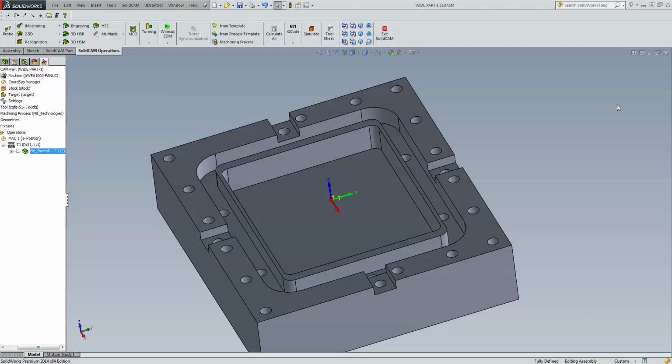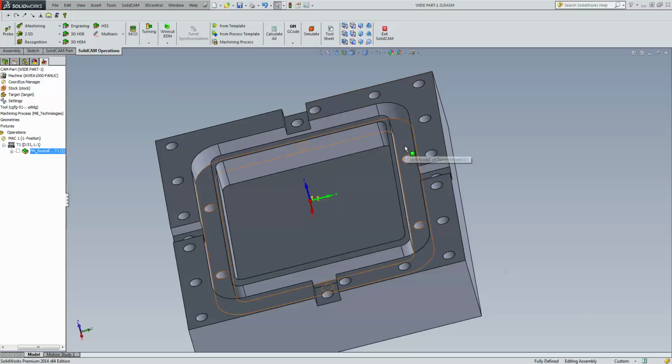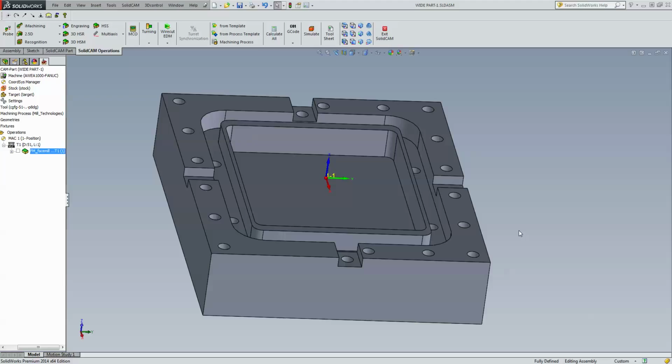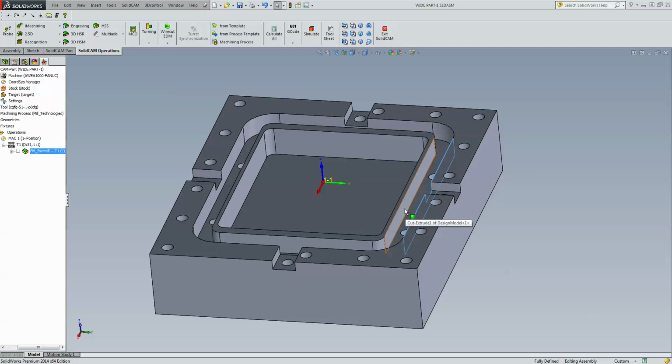And the way I'd like to mill this out is to first have an operation where the tool pass goes down the exact middle of this. Okay? And maybe even in a helical fashion going around. And after that, I have another operation of clearing off the walls. Okay, now the distance between this wall and this wall over here is a total of 10 millimeters.